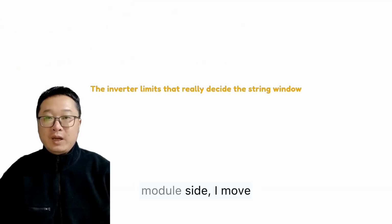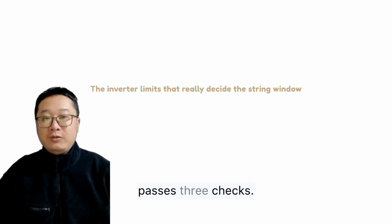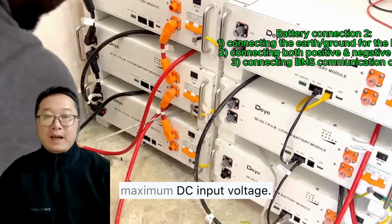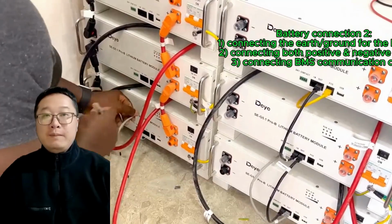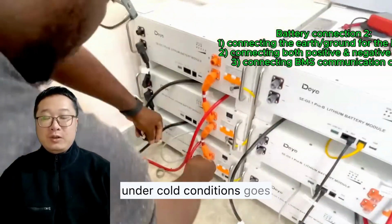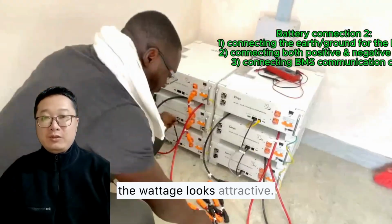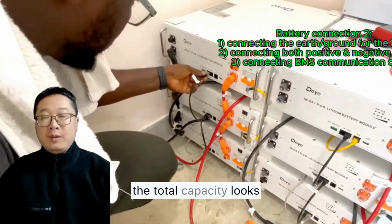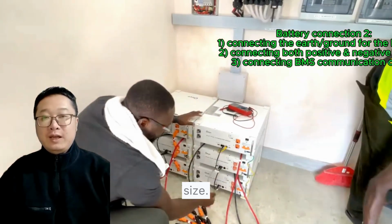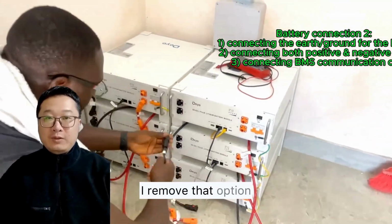Once I understand the module side, I move to the inverter side. And this is where the real design window appears. I only accept a string design after it passes 3 checks. The first is the maximum DC input voltage. This is the hard safety limit. If the string VOC under cold conditions goes above that limit, the design is wrong. I don't care if the wattage looks attractive. I don't care if the total capacity looks close to the inverter size. If the voltage can cross the DC limit, I remove that option immediately.